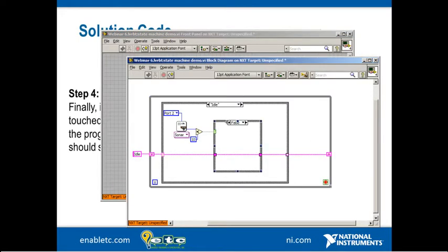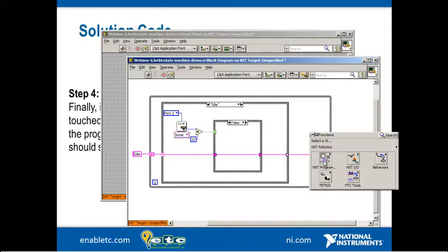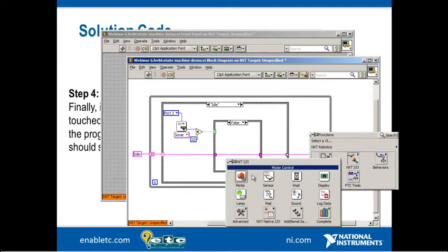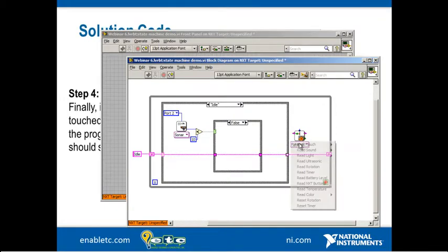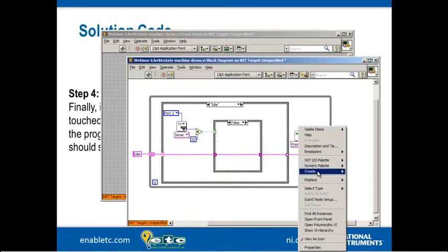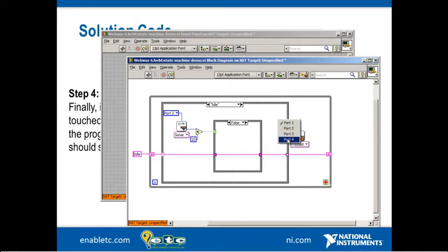And actually, instead of putting it inside the idle case, let's read our touch sensor by going to the NXT-IO palette, sensor block, pardon me, read touch pressed, which is the default behavior. Make sure we define our port, which for this robot configuration is port 4. And what we really want to do is, if this is pressed, we want to stop the loop. Well, we've got our loop condition here. We can just move it up to make our code nice and clean and read it here.